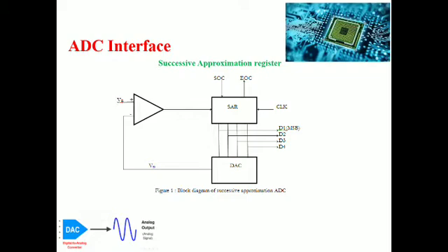Analog to digital conversion is the reverse process of digital to analog conversion. The A/D conversion is also called quantization, in which the analog signal is represented by equivalent binary data. There are a lot of techniques available: successive approximation register technique, counter type and flash type converters. Here we will go for the successive approximation register converter.